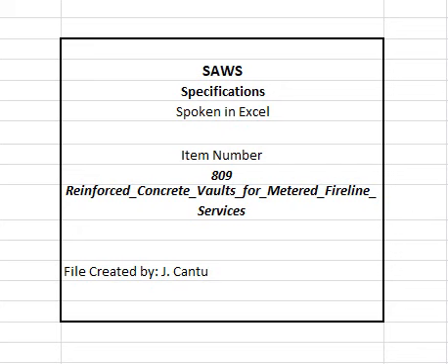3. Concrete used shall be transit mix and shall have a 28-day compressive strength of 3000 psi with a maximum slump of 6 inches and a minimum slump of 3 inches. 4. The use of admixtures shall not be permitted unless approved by the engineer. 5. Cement shall be Type I or Type 3 and shall conform to the general requirements contained in the materials specifications item 100 to 110 and the latest provision of ASTM specification C150 and C156 or most applicable approved equal provision. 6. Vault covers casting shall meet AASHTO M306 proof load criterion.